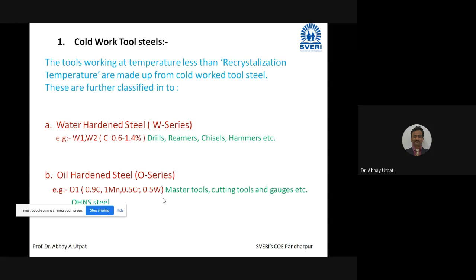Now, instead of forming a BCC plus orthorhombic structure, due to very fast cooling, the structure will be BCT. The long form of BCT is body centered tetragonal. This body centered tetragonal crystal structure is called martensite. And this martensite is harder than perlite.